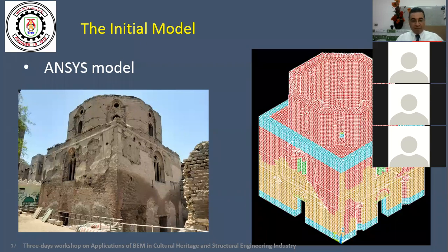But for a nonlinear problem, when you talk about the damage, and the damage might be, for example, slipping along the surface of the mortar versus the damage in the brick, then a smeared model will not be able to model these different damage scenarios correctly.